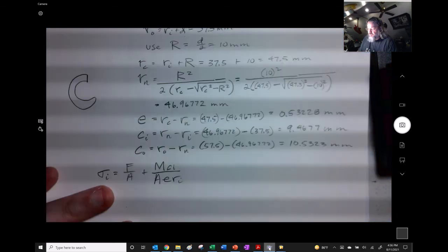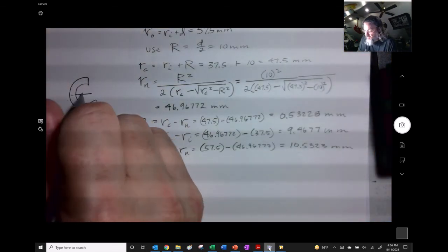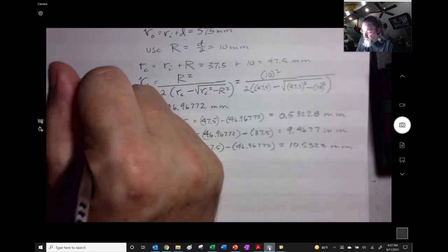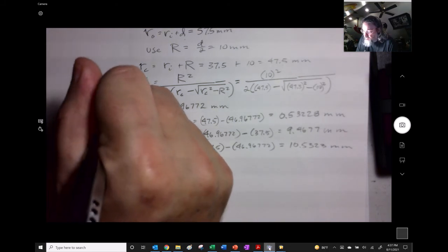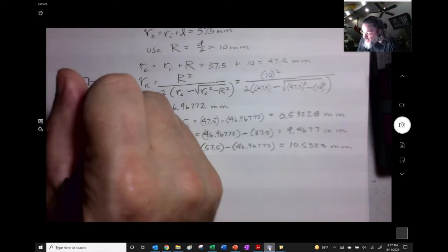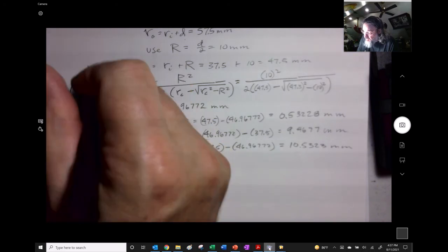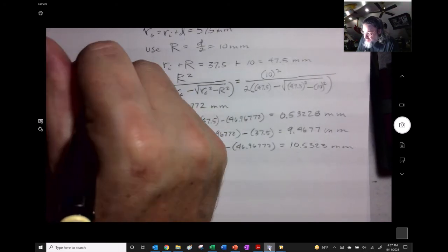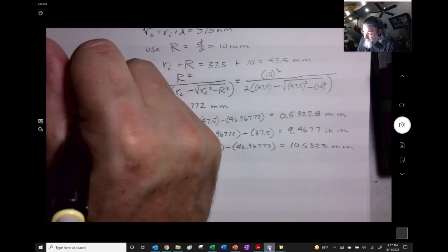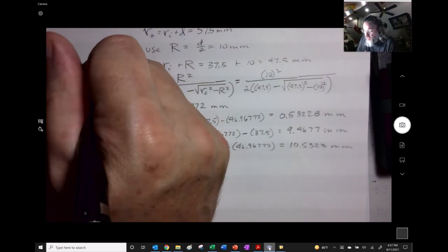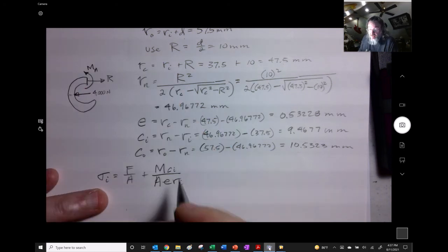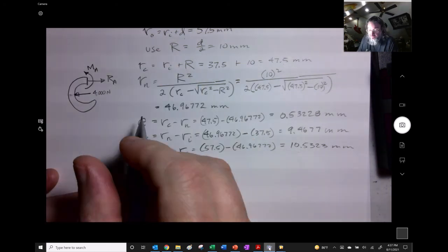We want to see the internal loads happening onto the thing. Here is our force of 4 kilonewtons, 4,000 newtons, happening right here. So we have a reaction right in there, and we have a moment. This one wants to go clockwise, so this one better want to go counterclockwise. So here's your M, and we'll say that it's an MA. This is RA right in there.